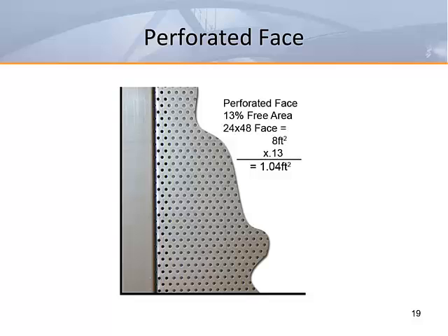Manufacturers of non-aspirating diffusers typically use a perforated face with a low 13 to 23% free area face. This results in a low velocity discharge airstream of clean air across the sterile field. A lower percentage free area is higher in pressure loss and sound, but provides a more even distribution.